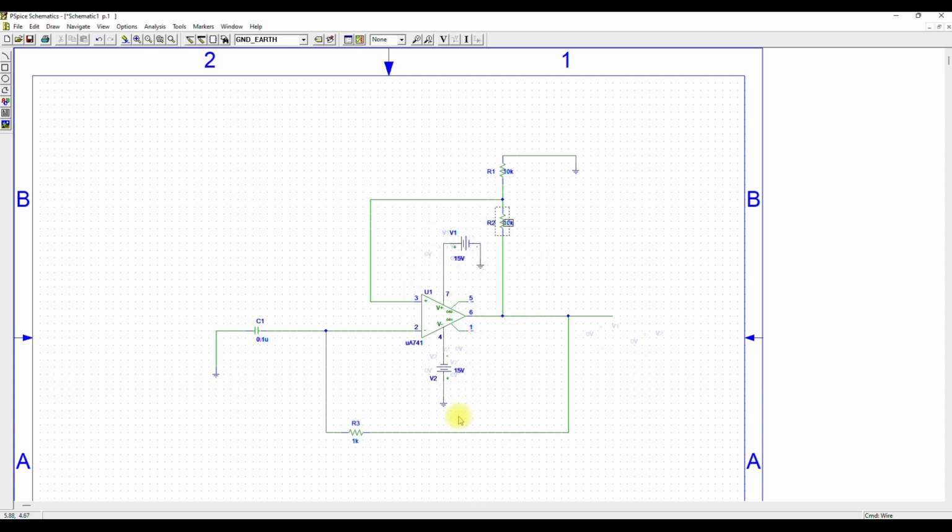And we have one more resistor, that is R3 between the output and the capacitor. So I need to change the value to 4.7 kilo ohm, as per the design. So this is the entire circuit connections. Basically one capacitor and 3 resistors, and we need to give 15 volt biasing to the op-amp.